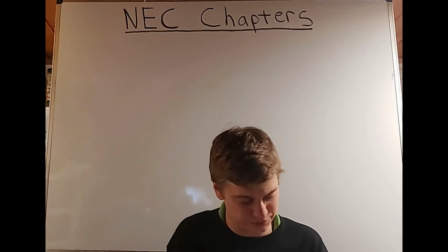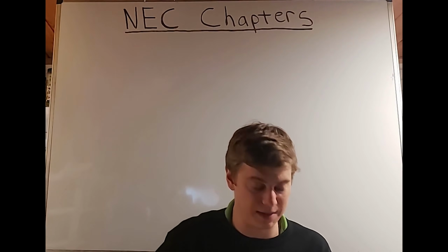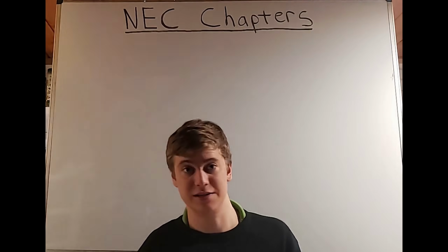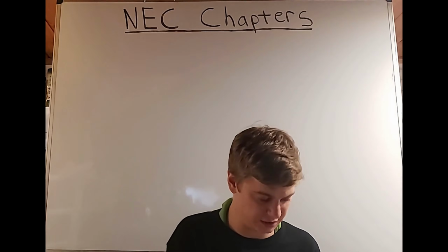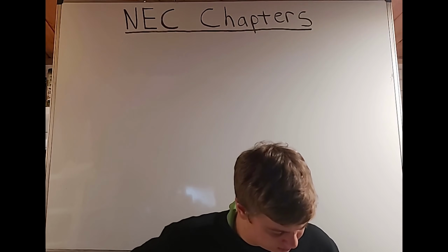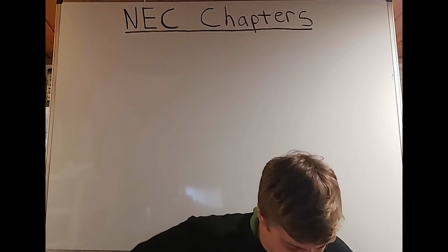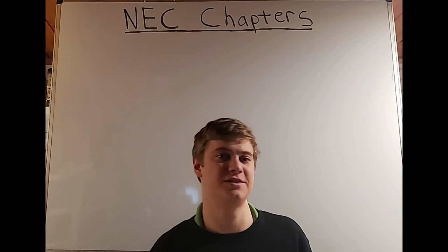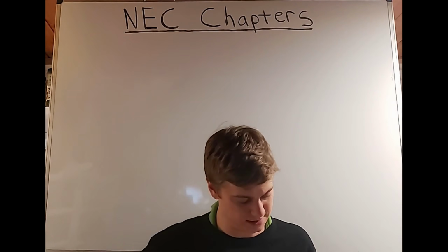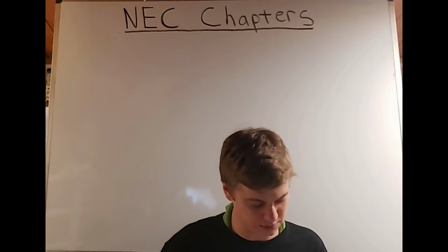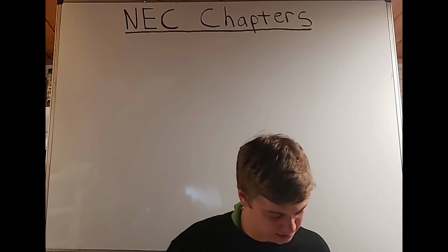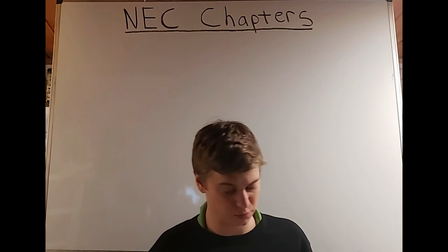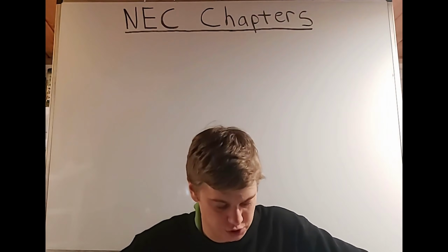So when it mentions paddle fans and we want to know the height in a bathroom, we're going to know where to find that. And we're going to find the support for the paddle fan in a different location, because remember, we're in the luminaire section right now, 410. Okay, and then we see number 2, it says luminaires located where subject to shower spray shall be marked suitable for wet locations. And you see above this mentions that it also includes if you're within that 8 feet parameter that they said that you have to be outside of. So if you're within that, then it's also going to have to be marked suitable for damp locations or marked suitable for wet locations.